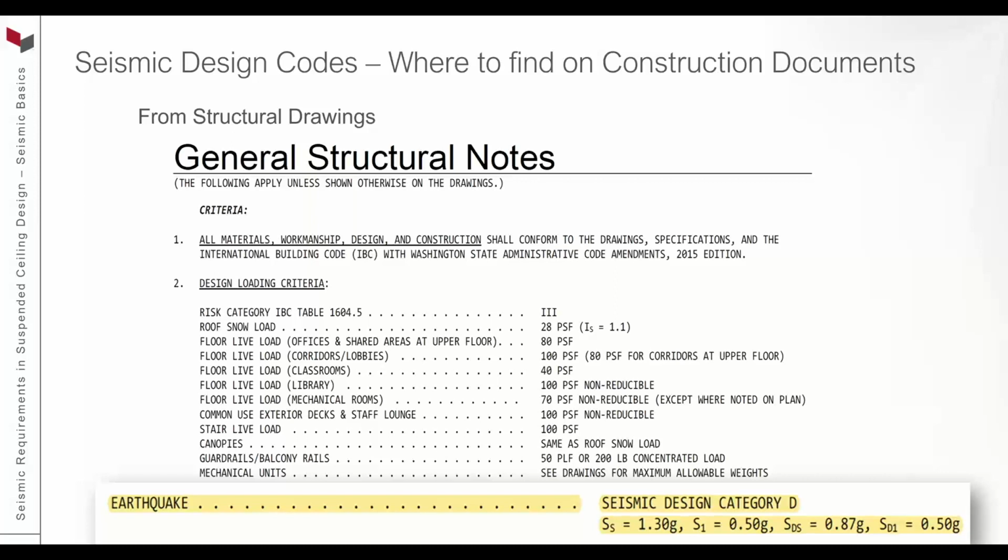So we were looking at the map earlier where we have reds and blues and greens. And so we look at this in the general notes and say, okay, the seismic design category that we're building in is category D. Down along the bottom of that, I'm just going to fill in a little bit of, these are seismicity ratings. So inside of that red zone inside of California, there's different numbers. The seismicity numbers change based on the intensity of the seismic area.